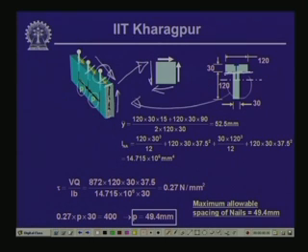So, if we would like to compute the shearing stress at this particular cross section, then we need to take the area above this section and take the moment of this area with respect to the neutral axis. First, we will have to find the position of the neutral axis of the cross section. If we say this is y bar from the top, then take the moment of all these segments with respect to the top part of it.